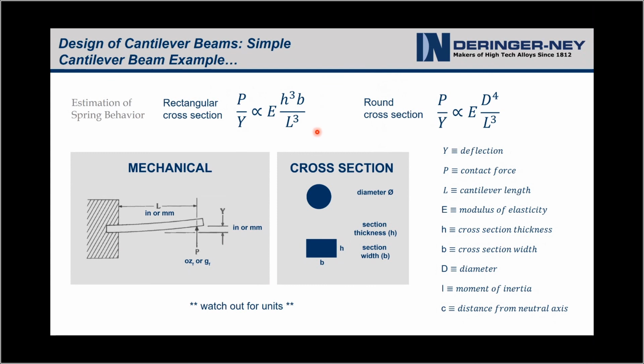So in selection of the mechanical configuration, what's the relationship between the spring rate and the geometrical attributes, right? So what are the stronger levers, if you will, to pull to control this spring rate? Right? So you see that it's linearly proportional to the modulus, say for a rectangular cross section, the modulus and the width of the beam, right?